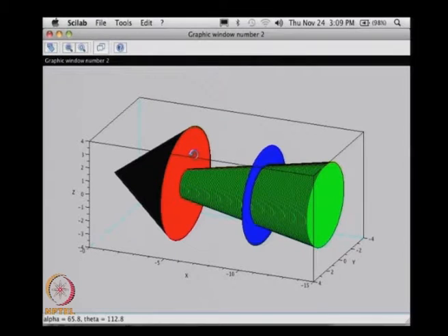The geometry is important. Why? Because that is the geometry of the shock itself, and its orientation with the free stream decides whether this is a 2D flow or a 3D flow. If you look at this shock structure over here, it is going to be pretty much the same even when the cone is at an angle of attack with the free stream. But in that case, however, we will consider the flow to be 3D.